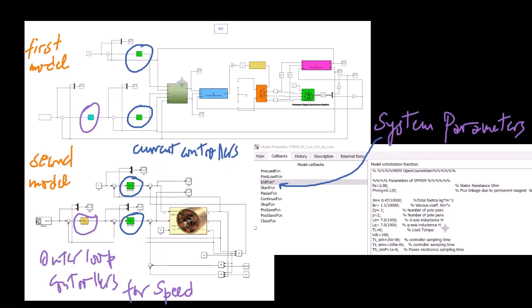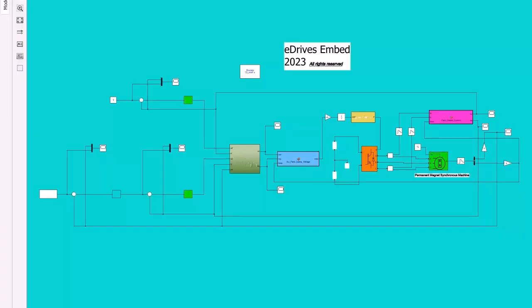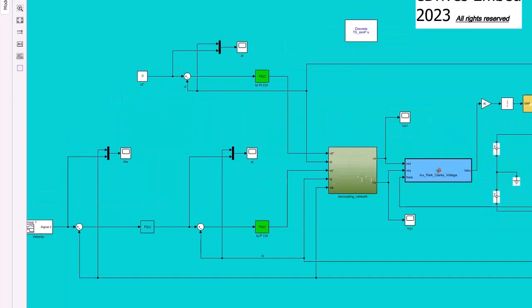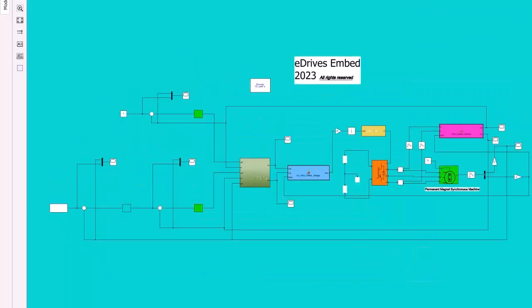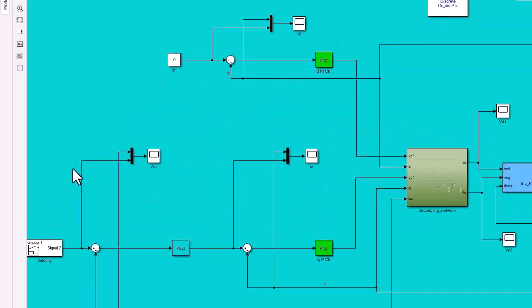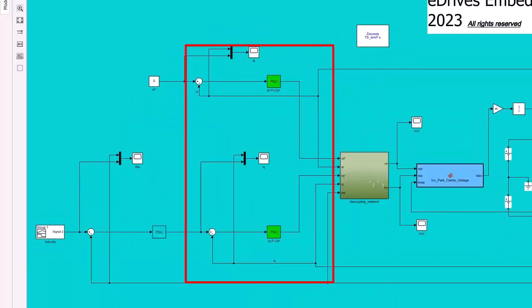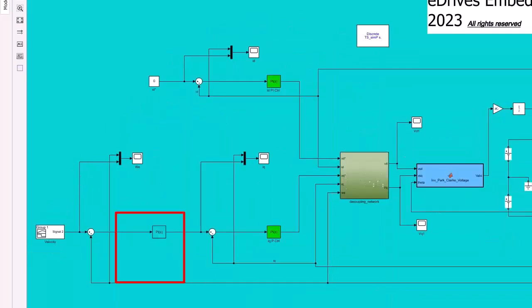All formulas for the design of the current controllers and speed controllers we have already calculated in the last videos. The complete PMSM speed control models I will of course provide. But my request is that you try to implement the whole thing yourself. Only this way, you can also make models yourself in the future, or even extend these basis models to future projects. We simulate the closed-loop responses by using PI inner-loop current control and PI outer-loop speed control.